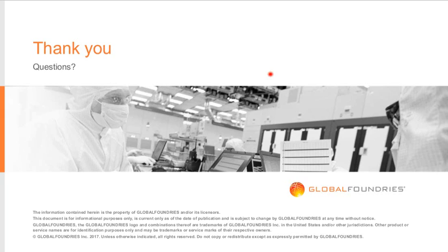For 100 gigahertz, we show the model hardware correlation for the DC and also the S parameter and noise figure, and we also do benchmark circuit design and use these circuits to calibrate the model for the LNA application, the PA application, and the switch application.